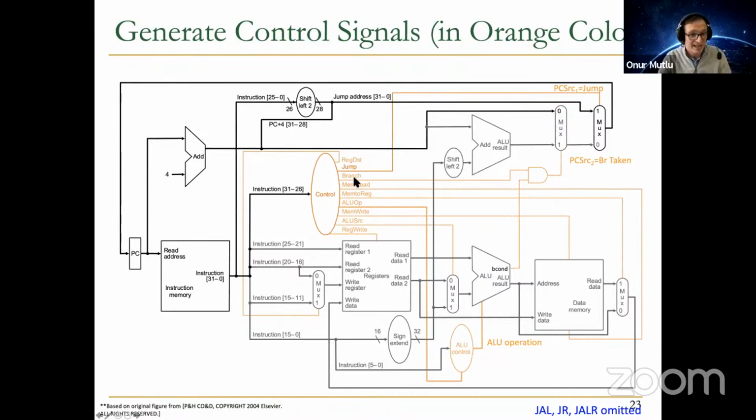You can see that there are actually 8 control signals, if I'm not mistaken, over here. They're single bit control signals. Well, there's also a PC source 1 and PC source 2 over here. They're control signals. So many control signals actually come from here, but some of them get processed based on the result coming from the data path. For example, this multiplexer is controlled based on whether the branch is taken and if the instruction is a branch, right? Then you actually get the target address as specified by the branch instructions, okay?